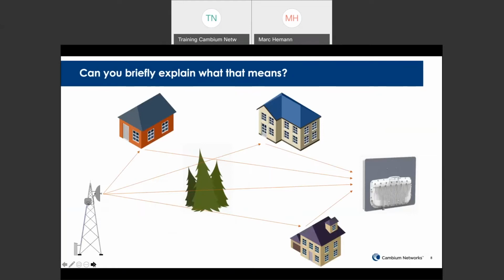The problem the legacy wireless networks and wireless devices had to contend with is a phenomenon called multipath. Let's remember, in its most simple form, Wi-Fi is all about manipulating airwaves. A transmitter sends out airwaves, and a receiver receives these airwaves. When a transmitting radio sends out airwaves, everything and anything the airwaves come in contact with, including open air, will affect the airwaves in a negative way. Airwaves can be reflected, scattered, diffracted, or refracted. This causes the original signal path to be split into multiple paths of that same signal.